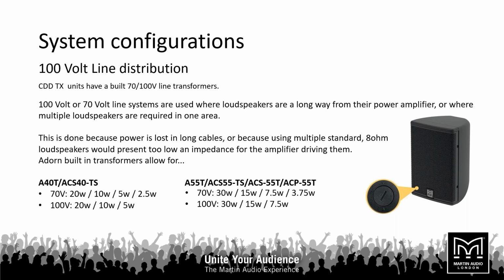If we pump 100 volts through this system, then this drop off is relatively more efficient, and therefore we get the energy at the loudspeaker as we want, and we step it down with a transformer in the cabinet rather than having that really high energy just blasting out of each loudspeaker.